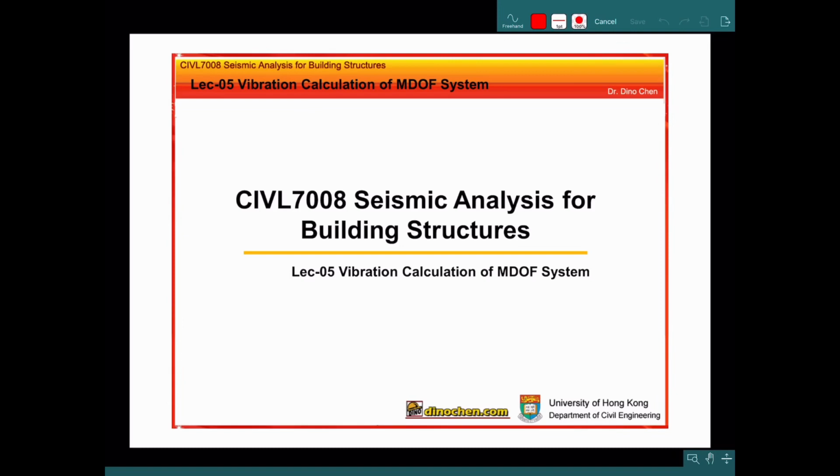As you understood from the previous lecture, we already introduced the modal analysis method for the MDOF system. Modal analysis is just to find the mode shapes and the periods of the different modes. This is the first step of calculating the vibration result of the MDOF system. Today, based on the modal analysis result, we will introduce the method to calculate the displacement and the internal force of the MDOF system. So let's get started.